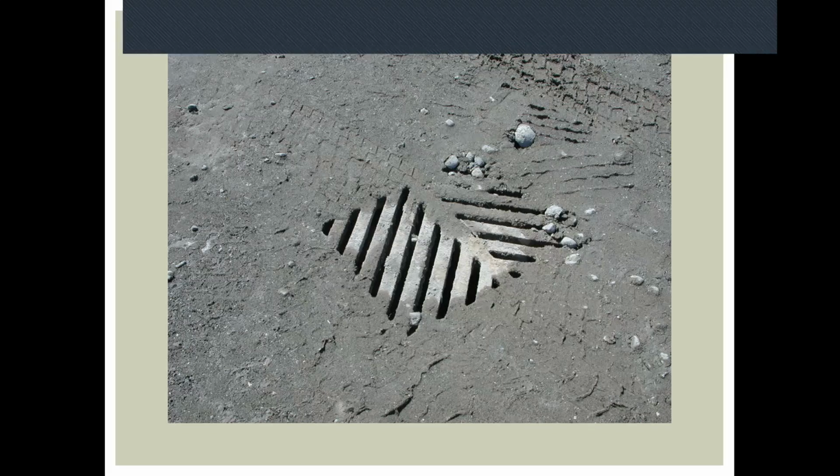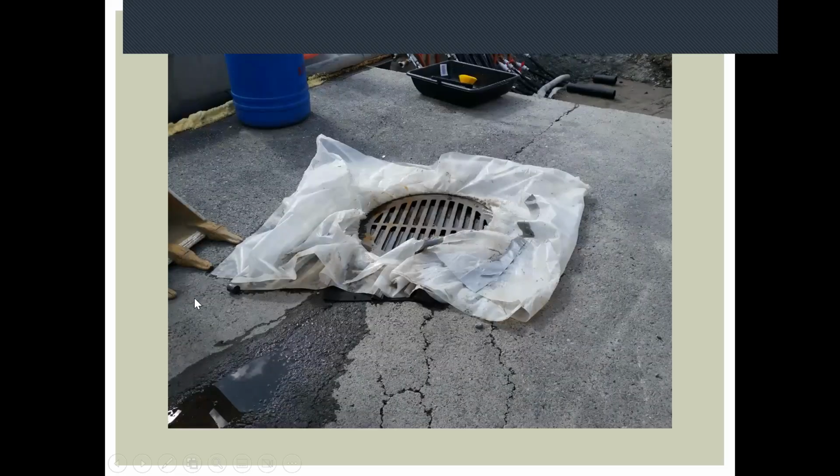So this poor catch basin, which doesn't have an insert in it, which again is great for all of the sediment that the insert would pick up, but isn't going to do anything for turbidity. So same question, is this a live catch basin? And in this case, it happens to be. So here is a practice. A lot of people don't like this, but if you are okay with ponding of water and you really want to protect a catch basin, to protect a live storm system, then just completely block it, either this way or put plugs in the pipes.